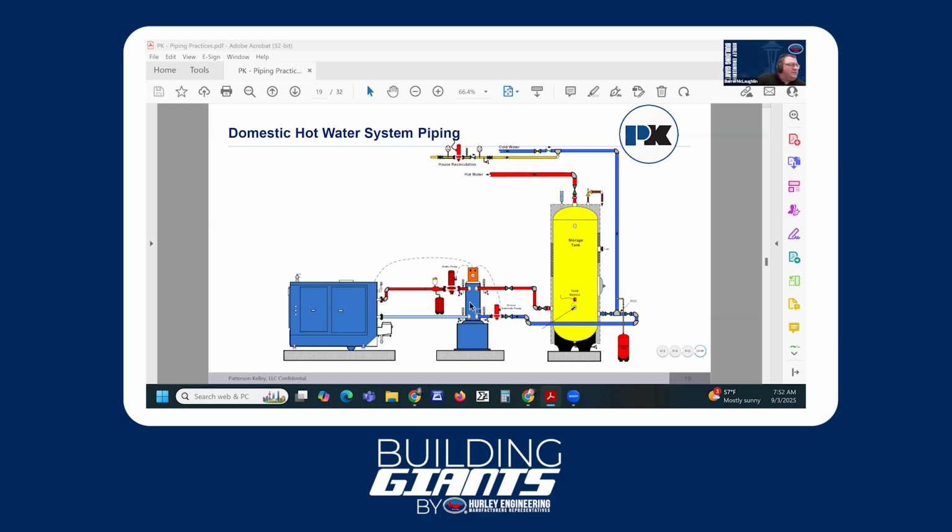With Patterson Kelly, the Duration water heater is our standard indirect water heater or heat exchanger. This could also be our Alfa Laval or SWEP gasketed plate heat exchangers. Absolutely. This is actually a braze plate, so that would be more of a SWEP. But any heat exchanger there would do the job, right? In this one, it does operate similar to a primary-secondary. We do have separation, but again, like I said, we have physical separation in the heat exchanger, not just hydraulic separation.